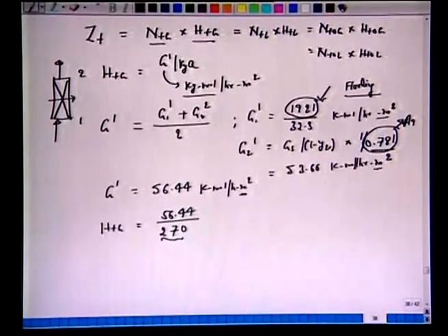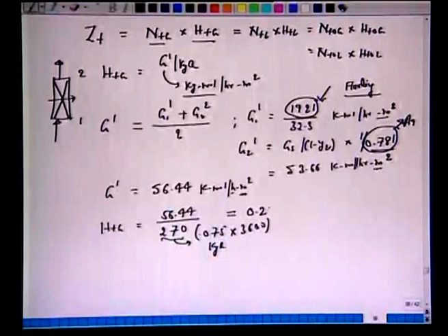So, how do we get this 270? It is given as 0.075 individual film mass transfer coefficient multiplied by 3600, because this is per hour and what is given in the problem is per second. So, we have multiplied this to obtain 270. This will give us 0.21 meter. So, the height of a transfer unit is 0.21. All right. So, that is the simplest quantity we have obtained.